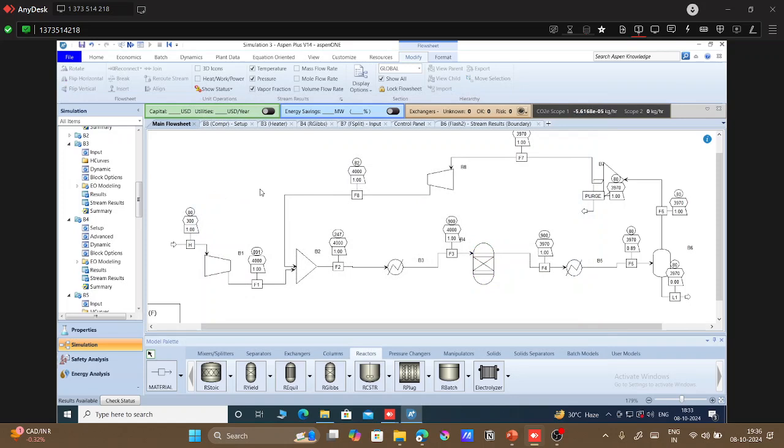So this is back in English units. At the compressor outlet, which is at 4000 psi, you can see temperature went from 80 degrees Fahrenheit to 891 degrees Fahrenheit, which when mixed, the mixture outlet is at 247 degrees Fahrenheit. This is because the recycle stream is at a much lower temperature. Because of that, the mixture outlet is coming at a lower temperature.